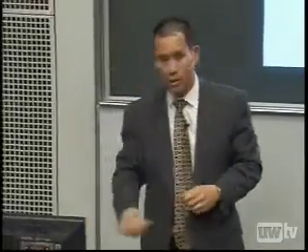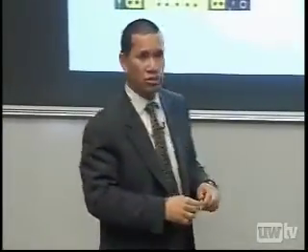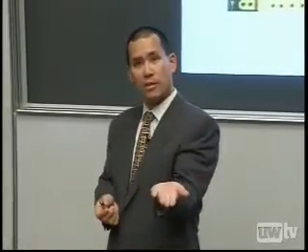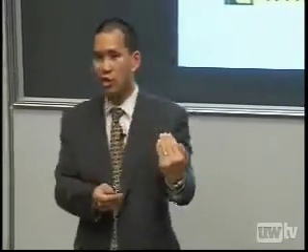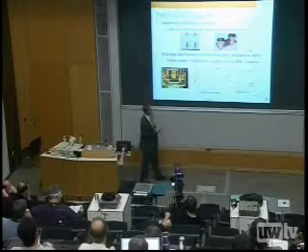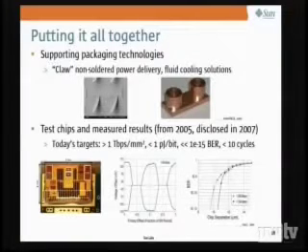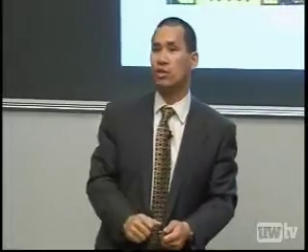Well, we've been working with Xerox PARC, Palo Alto Research Center, and they have this technology they call claws. They're metal hooks on a substrate that when you do a sacrificial layer release, they curl up. And these hooks, shown over here, are very springy. You can push a chip onto them and they scrub into the pads and they make a nice conductive path of about 50 milliohms, pretty low resistance. They can do insertion cycles of hundreds of thousands of insertions before they lose their springiness. So, you know, we need like 10.